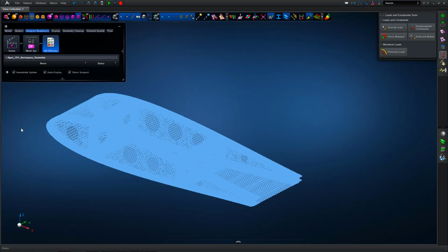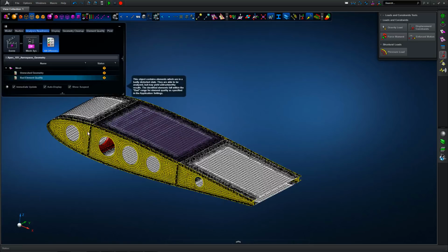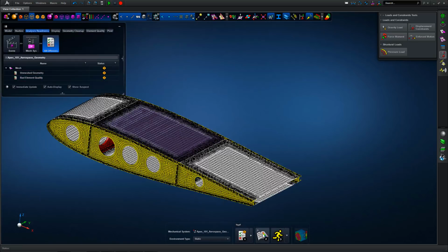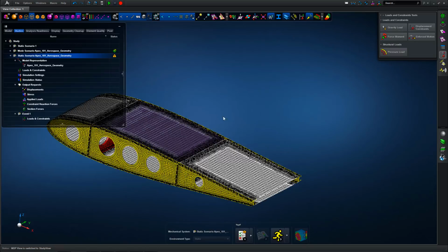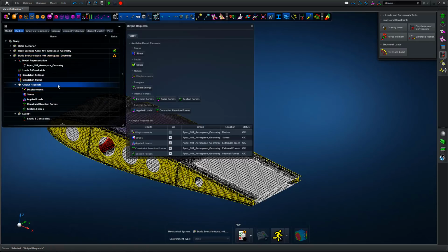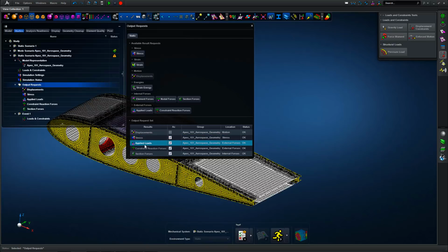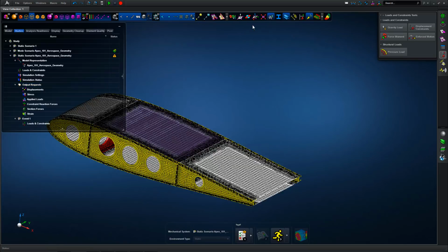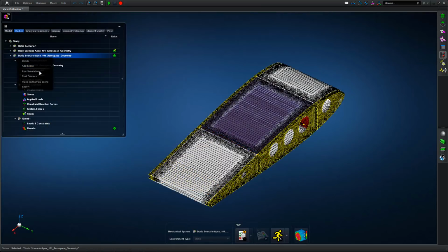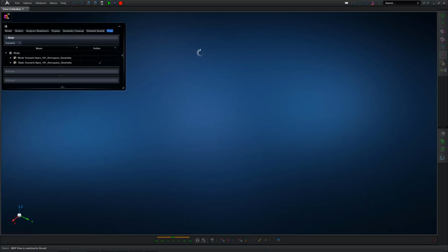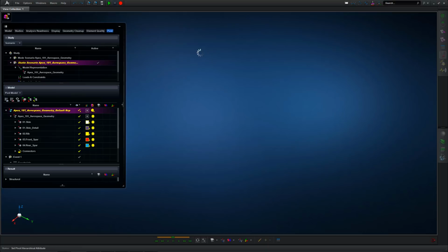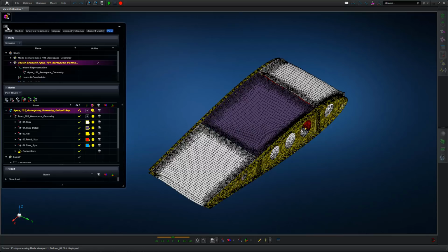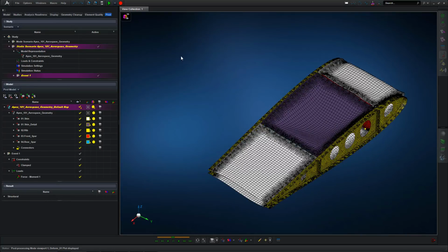So we've run a verification analysis so far, but now we're going to run through analysis readiness, and there are no issues with the model, so we know that the panel or the laminate definition is appropriate. For laminate analysis, it's useful to include, as well as the default output request, sometimes having laminate strain, so that the homogeneous strain output can be useful in understanding what's happened with the structure. So run the simulation and into post-processing, and then we can start to look at the behavior of the structure and how the laminate has behaved.